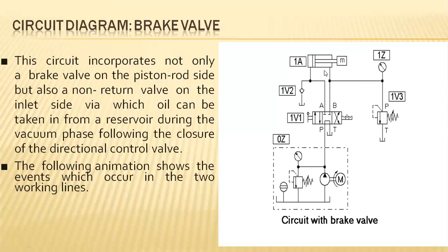So indeed to safeguard the situation, slow movement is required, because the highest pressure entering the inlet causes quick movement towards the forward stroke with high pressure. At that condition, the output line maintains a pressure relief valve that allows only a small pressure, which causes slow movement.